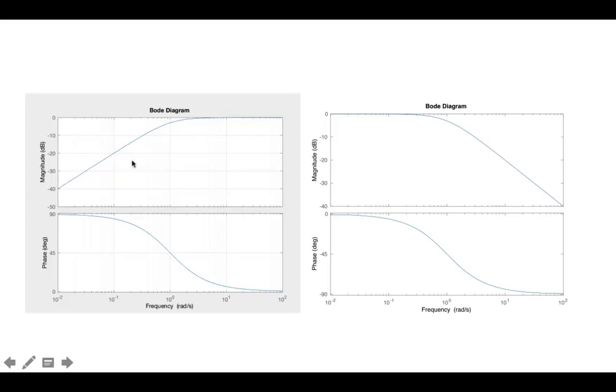Now on the lower frequency end, the high pass filter is rapidly transitioning to a gain of 0. So basically from this diagram we still have a behavior existing for lower frequencies. It's just it levels out at 1. So on the low frequency end we'd have this slope from this graph multiplied by 1 from this graph, meaning basically on the lower frequency end we'll just duplicate this slope.